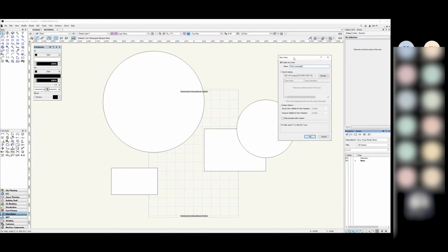So for instance, if I have my thinnest line weight having a line thickness of 0.1, then my medium line weight would have a thickness of 0.2, and then my thick line weight would have a thickness of 0.4, because it would be double that of my medium. And it's a really good system to work with, because it means that no matter what page size you print off, no matter what scale you're working to, if you're always using a doubling factor, you'll always be able to differentiate between line weights. I think it's a really good way to work.